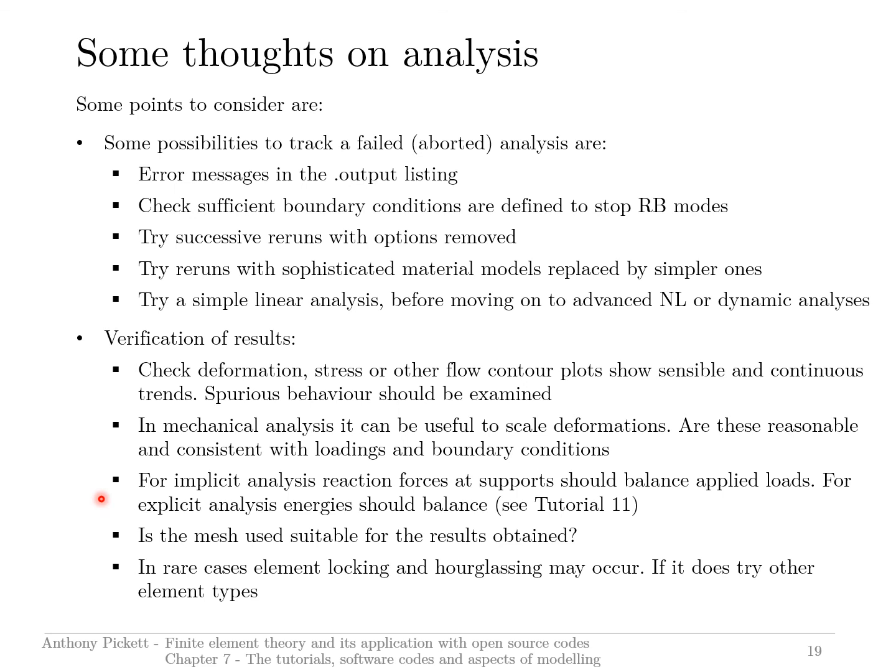I discuss this very briefly in lecture 2 regarding integration, but if you see these sorts of effects, then you're probably better off either improving the mesh or activating a different element type. There are usually, in commercial codes at least, elements that are less susceptible to locking effects or to hourglassing.